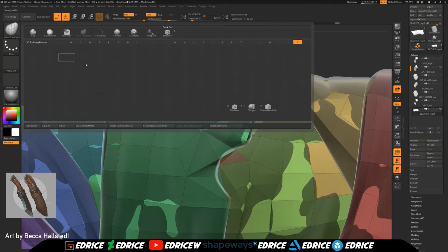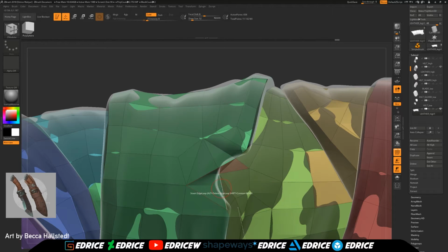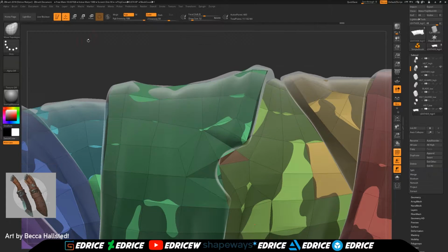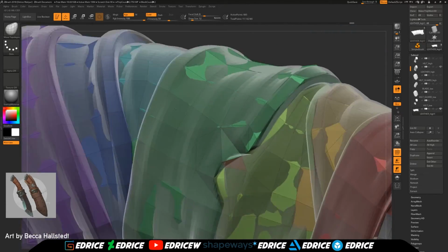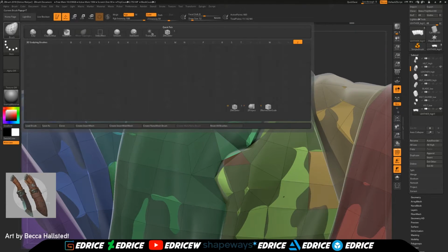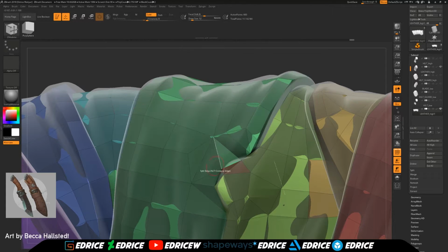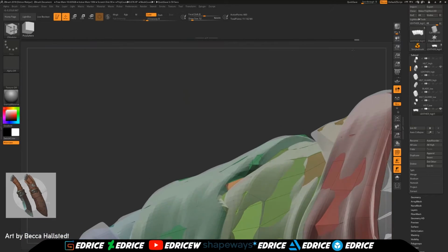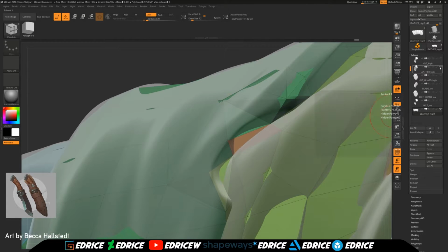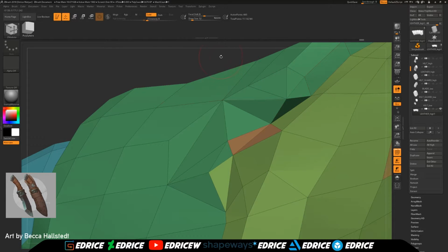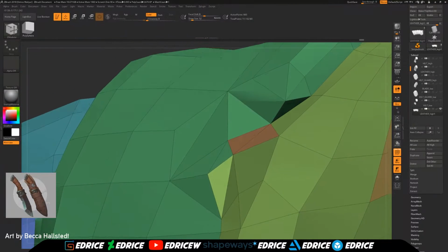And when you have complex parts like here, this is a good place to add some geometry, because that little indent inside of the strap is something very visible. It's a defining characteristic of that strap. So this is somewhere where you want to make sure that you have supporting geometry to make sure the silhouette is there, and that you have enough geometry to capture that when you make your normal map.